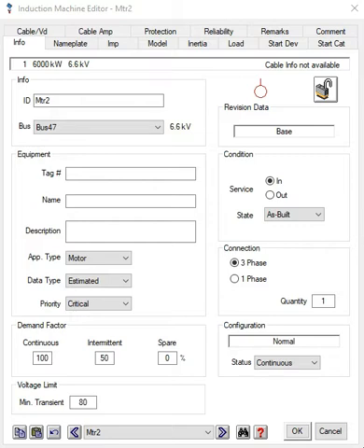And this voltage dip becomes the source of many problems. It decreases the voltage at the bus terminal and affects the overall motor starting performance. The motors that are running in normal condition may slow down because of this dip, and the voltage dip may also affect other electronics and sensitive devices.